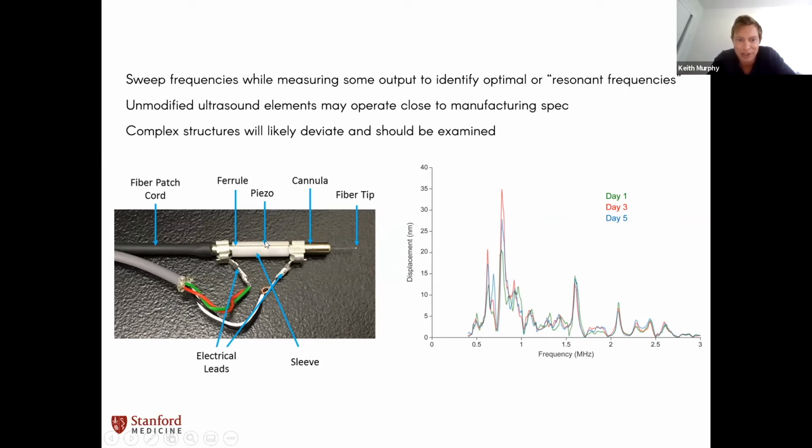I put a little single element piezoelectric crystal sandwiched between two metal tubes, and I was casting a voltage, like our sine wave and our fundamental frequency, across these tubes. This essentially created the voltage, and I would get an ultrasonic wave that would propagate through this entire structure. When I bought this piezo, there was an optimal frequency for just that element.